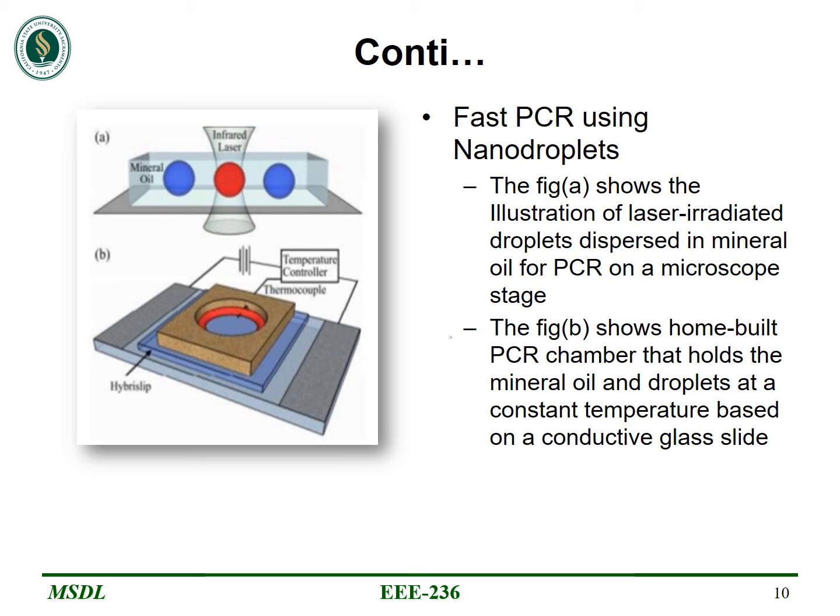With laser heating operated on a droplet, a convenient reaction chamber unit for miniaturized assay systems, many optical fluidic control blocks have been simulated using this system. A laser has been used for manipulation and mixing of droplets, and a droplet valve, sorter, fuser, or divider are all used in this system. The slide has proved to be an excellent method to mimic the classical microfluidic control on a planar surface.